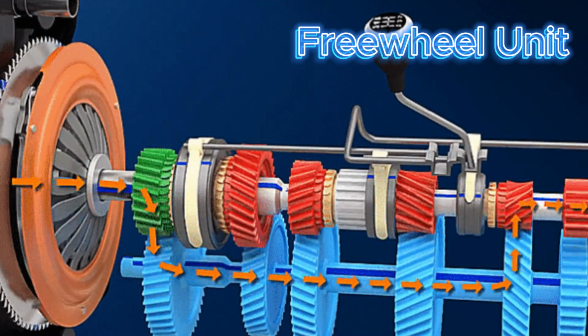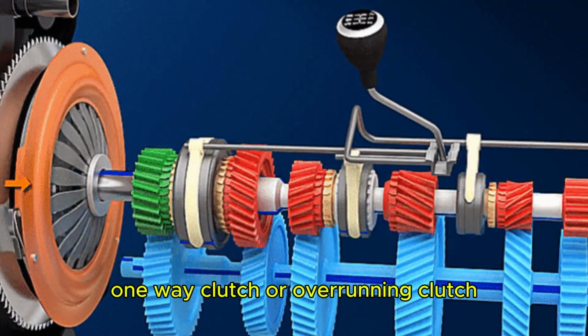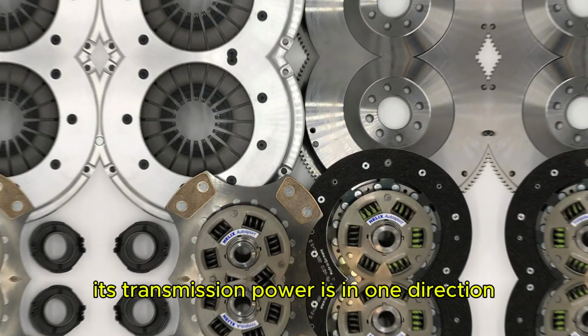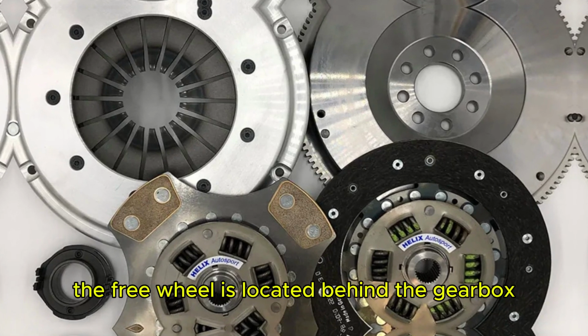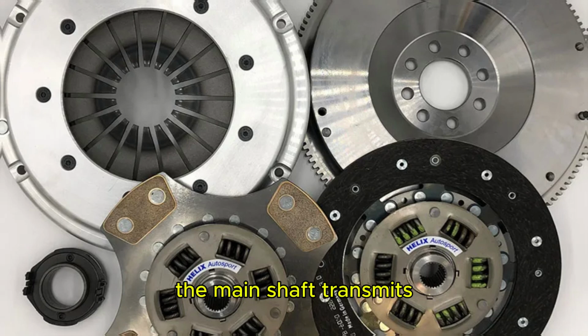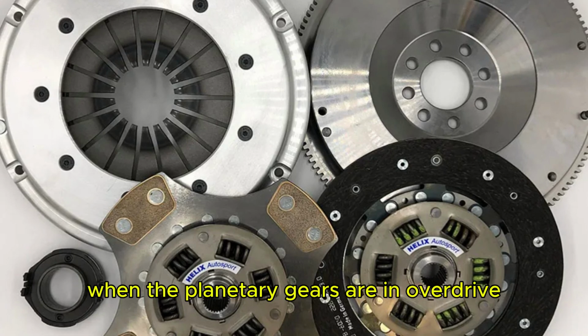Freewheel unit. The freewheel unit clutch is also known as a spring clutch, one-way clutch, or overrunning clutch. Its transmission power is in one direction, just as in bicycle transmission. The freewheel is located behind the gearbox. The main shaft transmits the power from the main shaft to the output shaft, which drives the output shaft when the planetary gears are in overdrive.